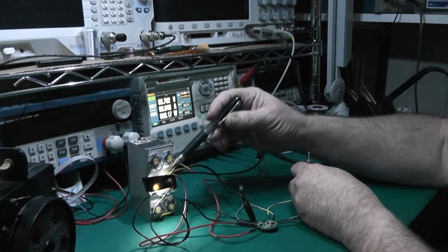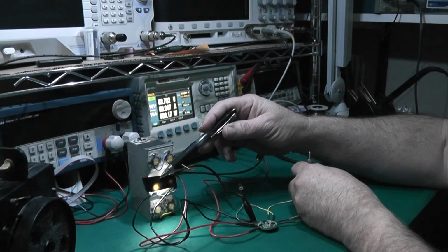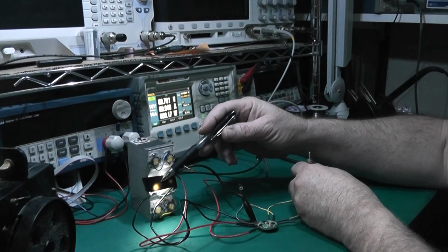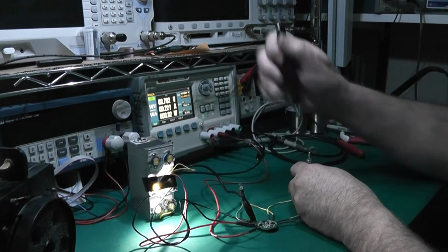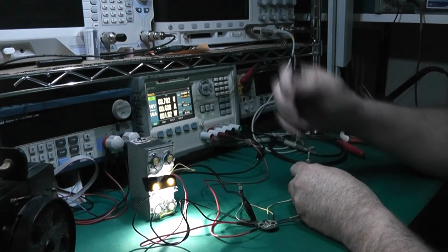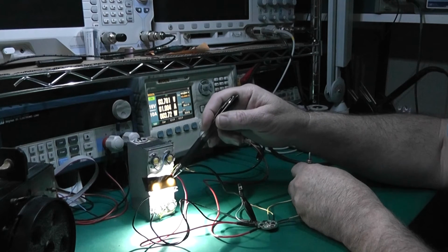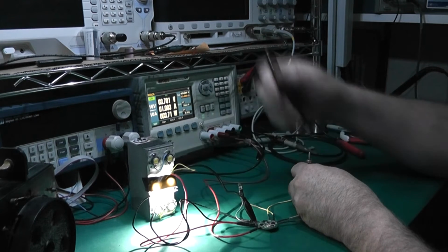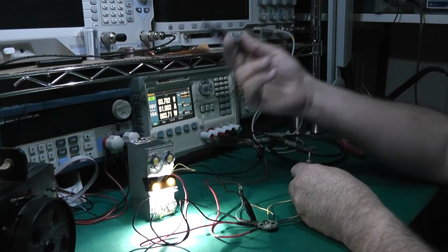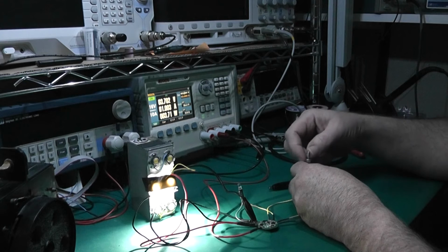Right now these are configured such that the channel 2 LED is off and the channel 1 LED is at level 1 in terms of drive. When we go to mode 2, we're going to level 3, and this is still off. Both level 3, level 4 and off, and both at level 5. And at 500 milliamps, what we see is 1 amp drive, 500 plus 500. We can obviously program through the menu system for different current tables, but by default it's set to the 500 milliamp current table.